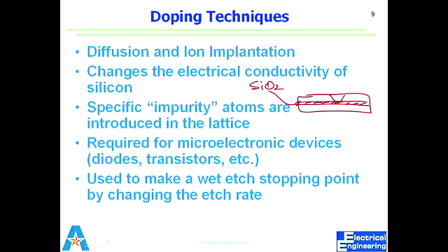So we put them in a furnace again and raise the temperature really high, and we introduce those gases which you want to diffuse into silicon. That's one way we do doping. The other is by force, where we can inject them. That's called implantation. But the basic idea is that we do this to introduce specific impurities to change the electrical behavior of semiconductor materials.